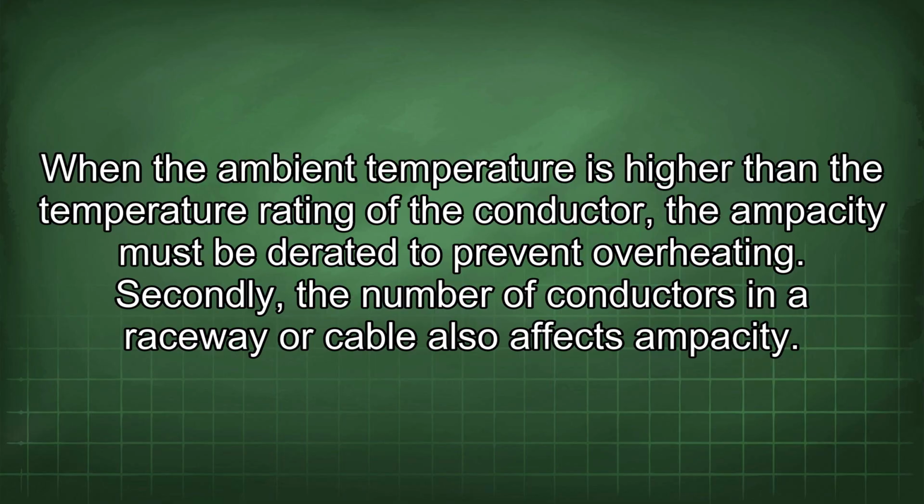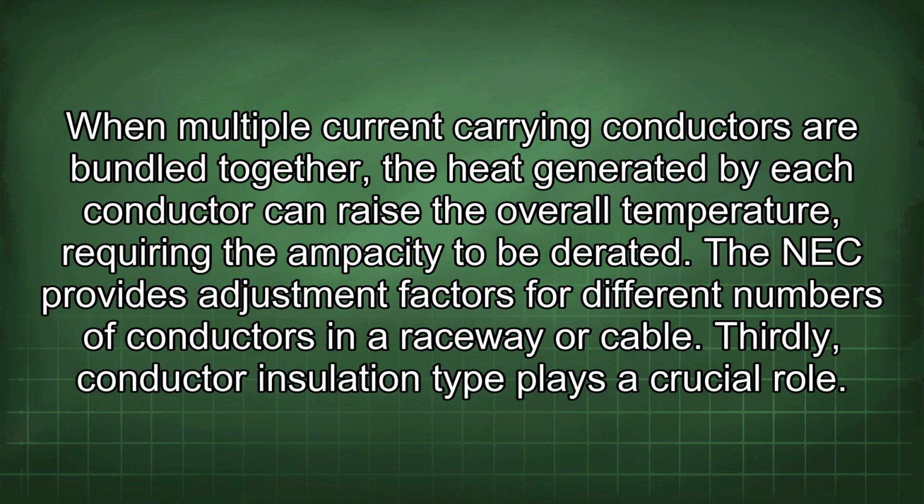overheating. Secondly, the number of conductors in a raceway or cable also affects ampacity. When multiple current-carrying conductors are bundled together, the heat generated by each conductor can raise the overall temperature, requiring the ampacity to be derated. The NEC provides adjustment factors for different numbers of conductors in a raceway or cable.